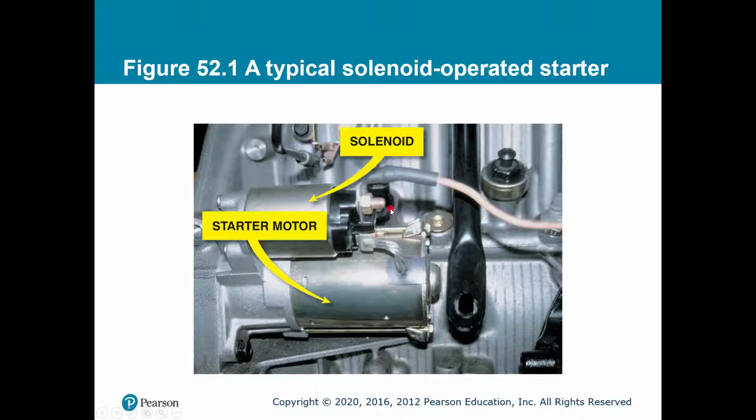Really, technically, it's B for bat and S for signal. Those wires are important. So there's 3 terminals on a starter solenoid. There's one for the B, there's one for the S, and then there's a third one down here. You can usually see it's an uninsulated braided cable, and that wire is the M nut, right? So as current passes through, the switch exists between the B terminal and the M terminal and carries current down into the actual starter motor.